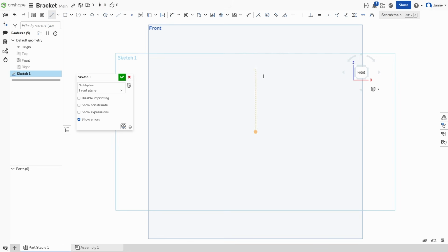We're going to create a line, so we want it from the origin, but we're going to start here, go down to the origin, and that's about 2 inches. That's exactly what we want. So we just got to go roughly 2 inches, and then we type in 2, enter, and hit escape to get out of that. Let's hit D for dimension, or we can go over here. We can click on this, and we can click on this, and 2.